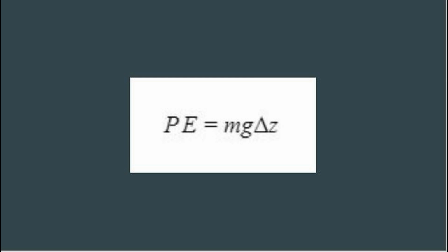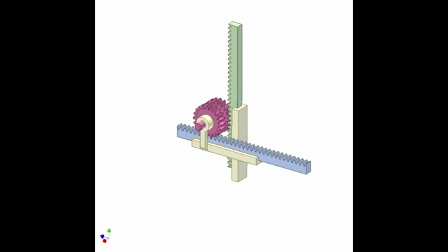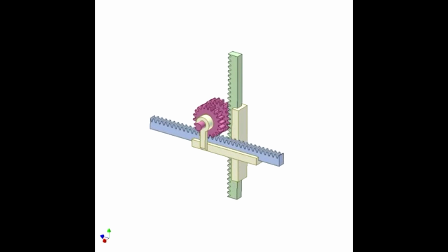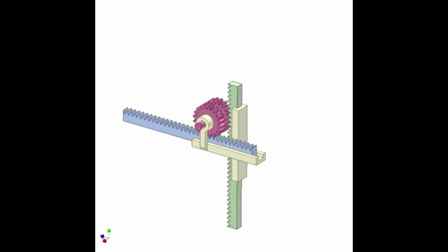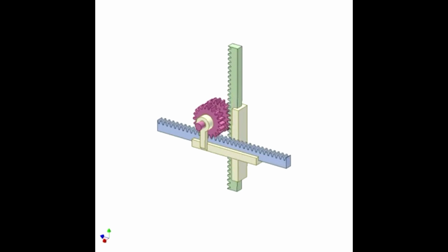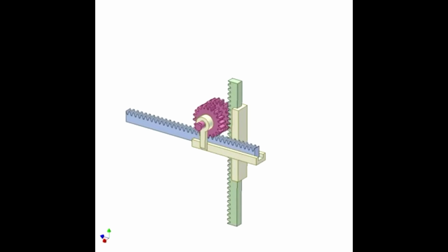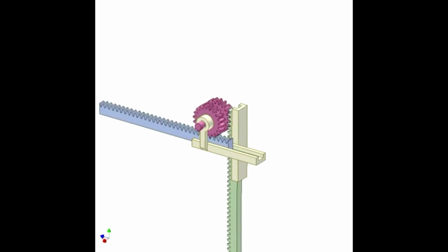We plan to measure our stored potential energy as the weight of the mass times the height, delta z, it was displaced. However, we built our system forgetting that in order for the ratchet gear to turn, it needed to be interfaced with the pinion gear. So as the pinion gear reversed directions, the ratchet stopped spinning. Since the two gears are connected, the pinion gear stopped spinning too, and our piston did not move down. We had the right idea, but our system was flawed.